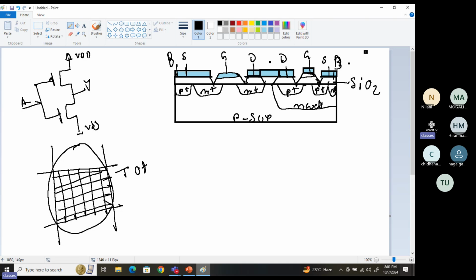You have to tell that first we will put SiO2, then we will make and put the mask, and put light on the top of this. A photoresist material will be there, which helps us etch that layer. After that we apply HF or nitric acid, then it will go out, and that particular design will get embossed on the substrate. You have to explain up to the metallization part.